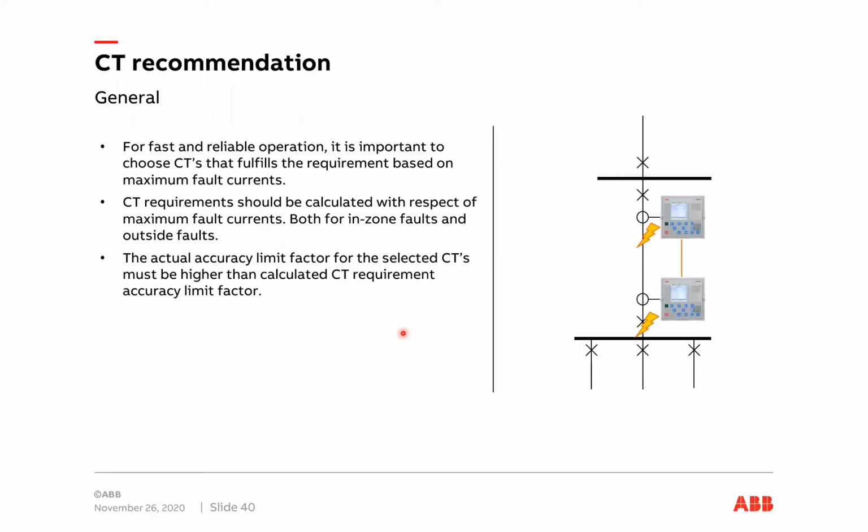So when calculating the CT requirements, it should always be done with respect to the maximum fault currents.